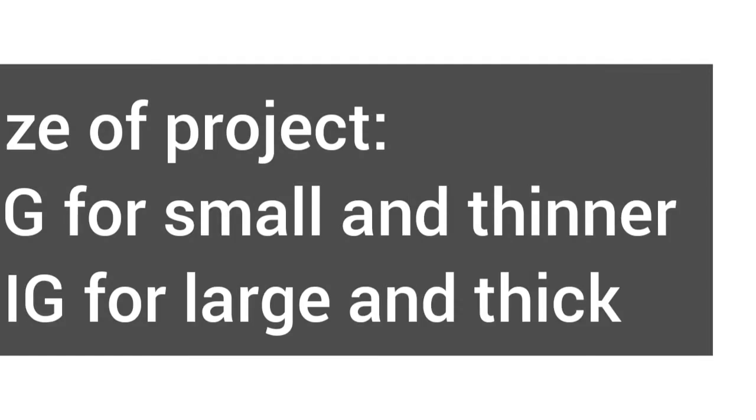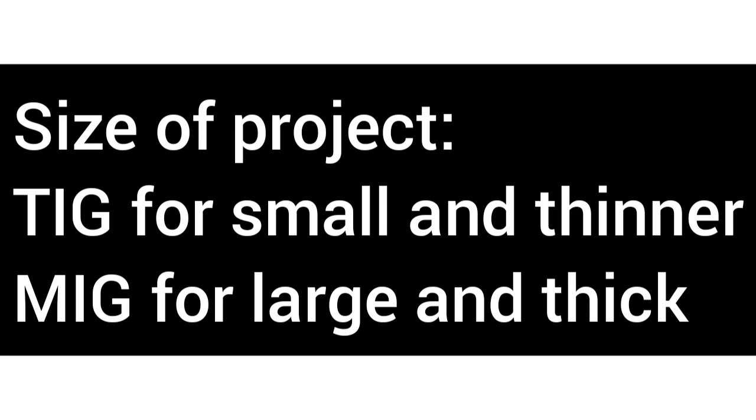The size of your project could determine which form of welding to choose. TIG welds are better for thinner metals and smaller projects because they produce precise and clean welds. MIG welds work well with larger projects with thick metals that need a longer continuous run.